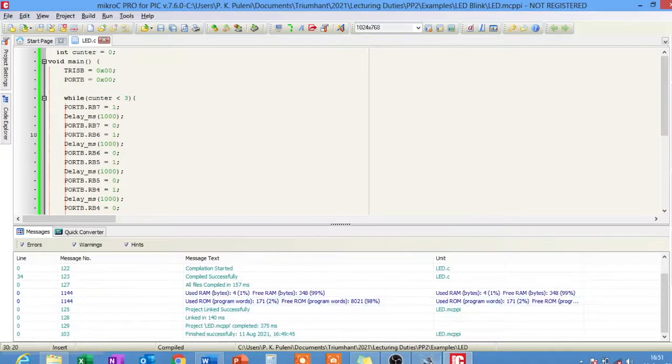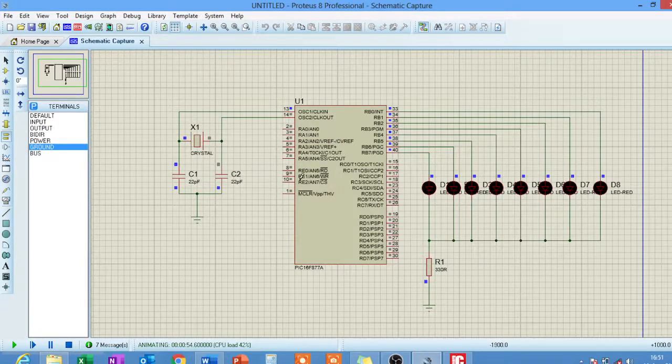and we have just successfully programmed a circuit whose function is to turn on and off 8 LEDs in a sequence. All right, if you feel your LEDs are not bright enough, you could reduce the value of this resistor. Otherwise if you feel they are too bright, you could increase the value of the resistor. But in practice, please make sure that this resistor is not too small, because otherwise if the resistance is too small, you send a lot of current through this, which can destroy the LED.